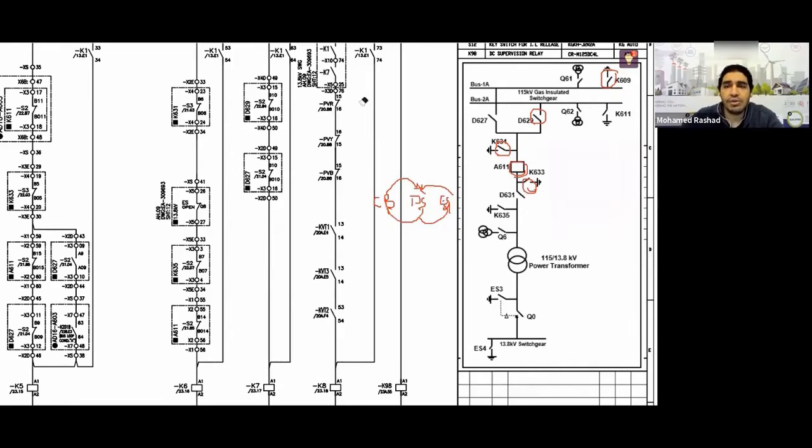Okay, the condition I'm talking about now is a different condition. What is it? It's that the feeder is actually energized, meaning this is closed, as I mentioned, and the breaker here is closed, and this disconnector is closed, and this transformer is now energized and supplying a set of loads below. What do I want to do now? I want to take this bus out for maintenance. So, to take this bus out for maintenance, it's very simple. I can open the breaker, open the disconnectors, close the new disconnector, and continue with my work.